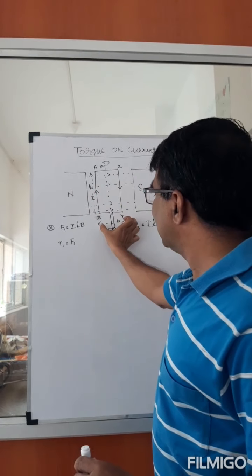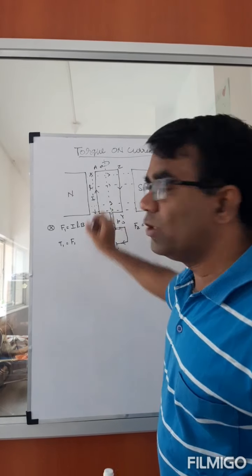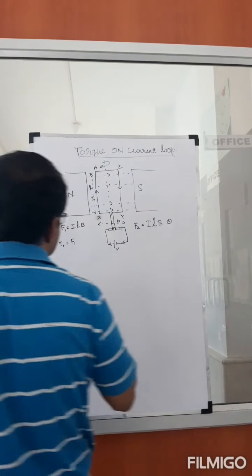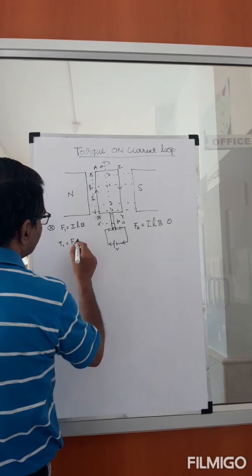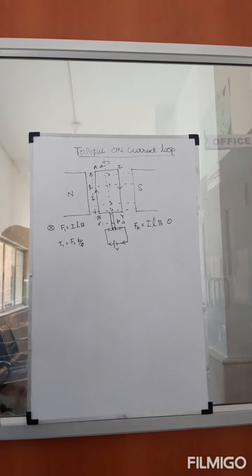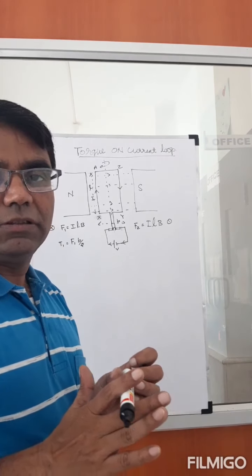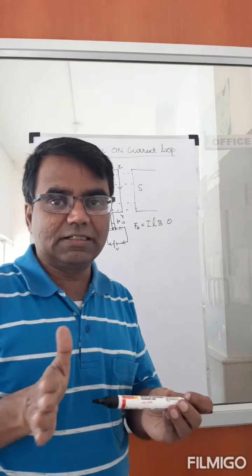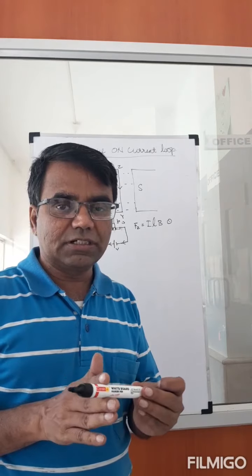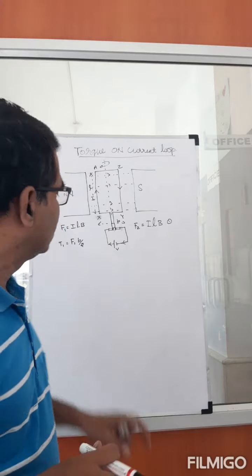This is B, the total width of the loop, and from the axis this is going to be B by 2, half of that. So that is what I will get all the time. The force acts in this direction, the force acts in this direction, and from the rotational axis you get B by 2. So that's the torque here.